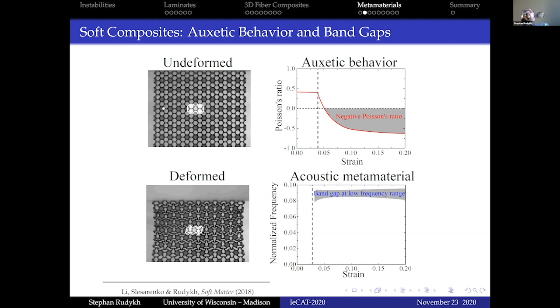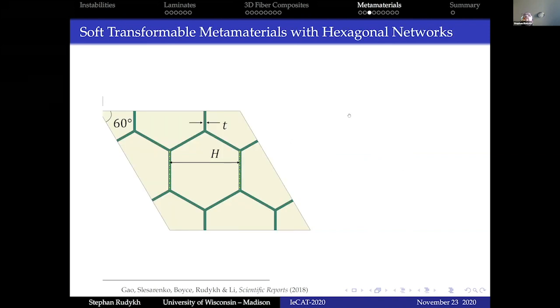You need to say, of course, with this material, there are lots of band gaps that always exist without any deformation. You don't need instability to get there. It's just they will be at higher frequencies. And the typical challenge is to open band gaps at low frequency, so you can create a reasonable size of microstructure and put it on the wall or on the window and filter noise. For example, that is an application for that. And that may be related to the auxetic behavior, because that's where you can probably manipulate the pressure waves that are typically not that easy to control with soft materials.